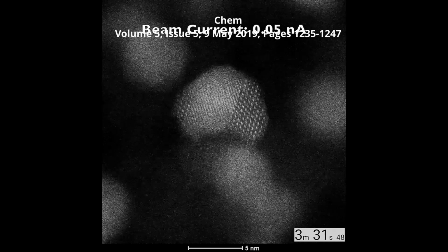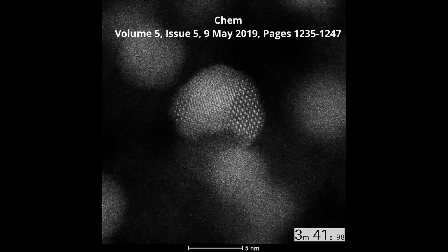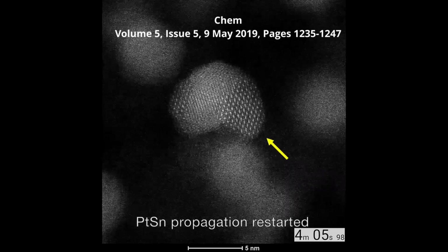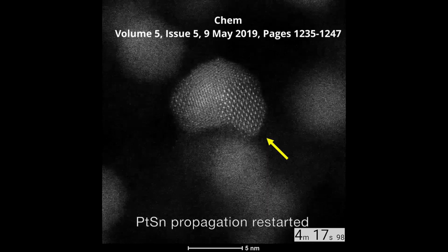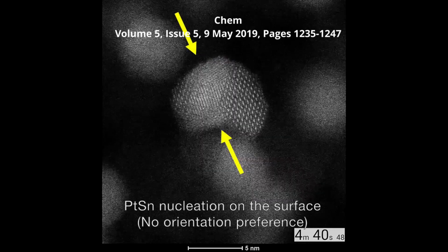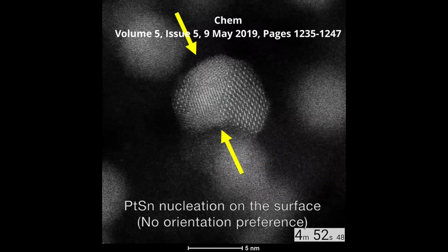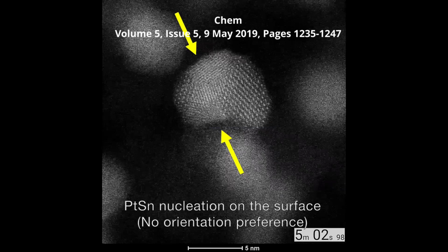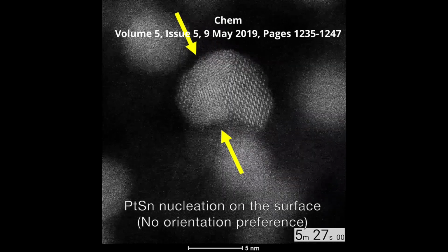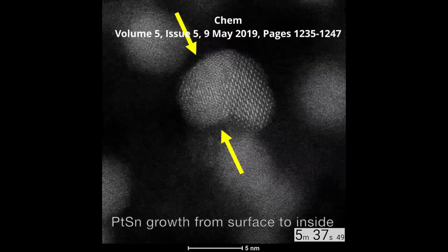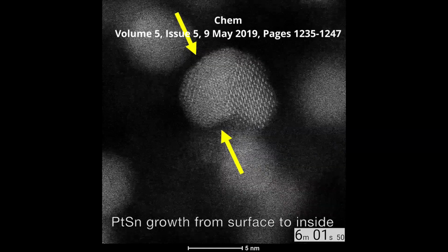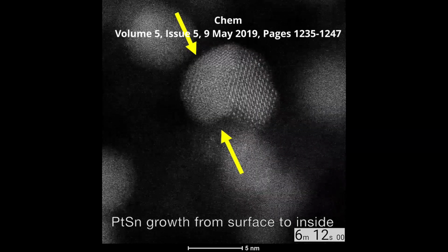Moreover, steps will need to be taken to overcome the reaction's biggest drawback, that it is limited by equilibrium conversion and by side reactions at high temperature. Also, alternative catalysts, most notably metal oxides such as gallium oxide, molybdenum oxide, or vanadium oxide, have received significant attention over the last decades, but a practical alternative to the platinum-tin and chromium systems has not yet been developed.